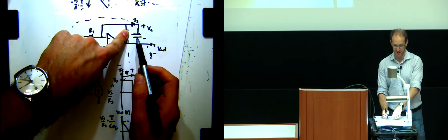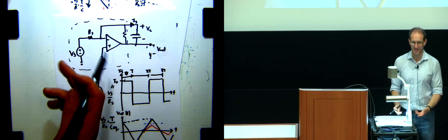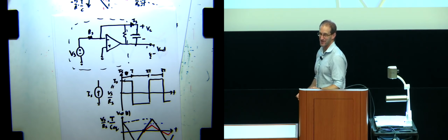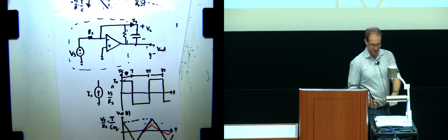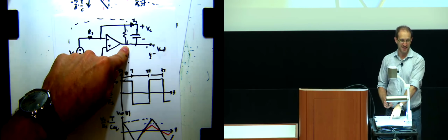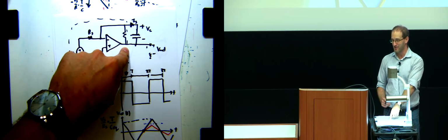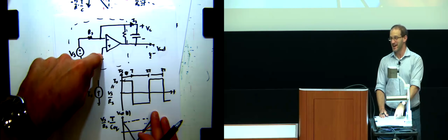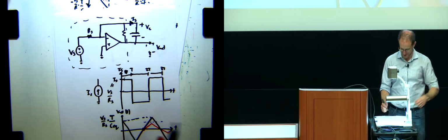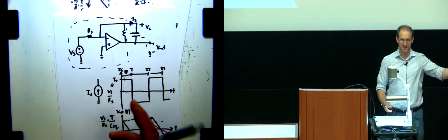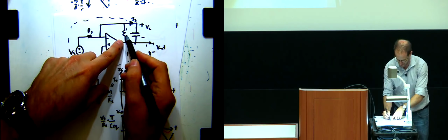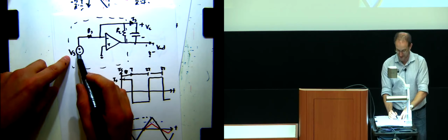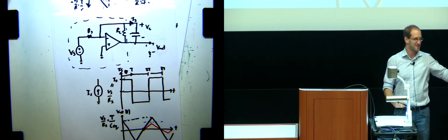If the capacitor is an open circuit, then actually you're not really in feedback on average, right? You're only in feedback when you make changes at the output. So all this resistor is doing, when you add it back in, is trying to make it so that, on average, this op-amp is in negative feedback. If it is in negative feedback, then on average the value of Vout should also be 0 volts, because it'll be minus whatever this resistance is, let's call it RL, divided by RS times Vs. And on average, we said Vs is 0 volts.